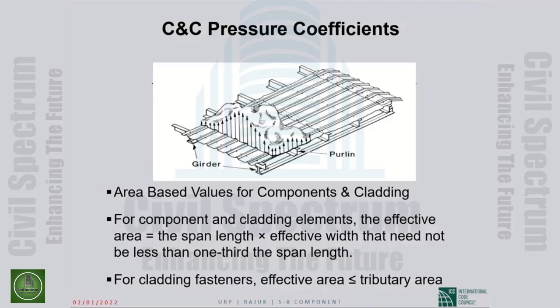So effective area is like tributary area, but not quite the same. The larger the effective area, the lower the pressure on component and cladding.